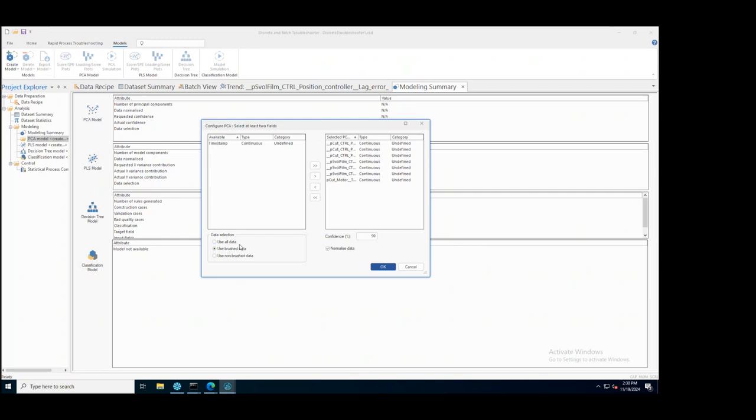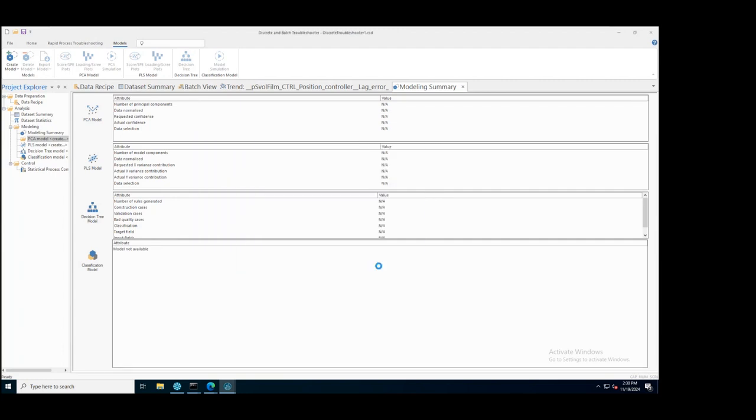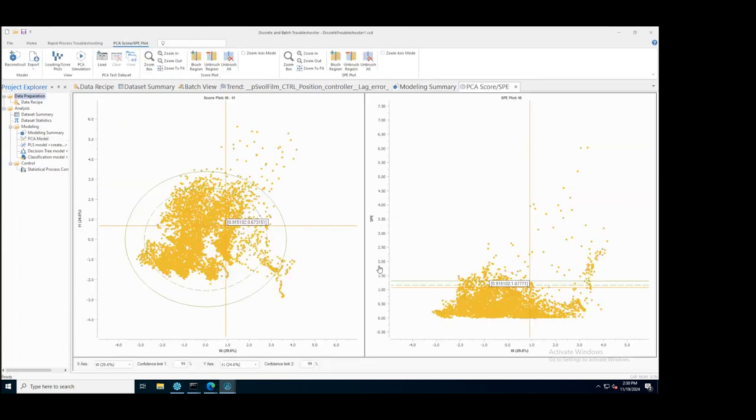So we're going to use all of our brush data, and this is the data associated just with our new blade, and that's important. We want to build a fingerprint and a definition of our system just for a new blade. So here you can see why we call it a fingerprint. It looks like a fingerprint. We have a projection of all of the data in our system from all of our tags into this new coordinate system. And this new coordinate system is our principal component system.